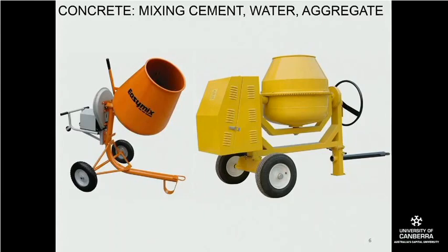But basically you can add aggregates like sand and crushed stone to the cement, and the resultant thing that you get will act as one homogeneous lump, like a big stone. Okay, and this is because the cement reacts with the water and sticks to everything that it's exposed to. The reason why you use aggregates is basically because aggregates are cheaper than cement. So the aggregates are there to pad out the concrete, so you don't have to use too much concrete, because the concrete is the thing that goes through the most processing and costs the most.